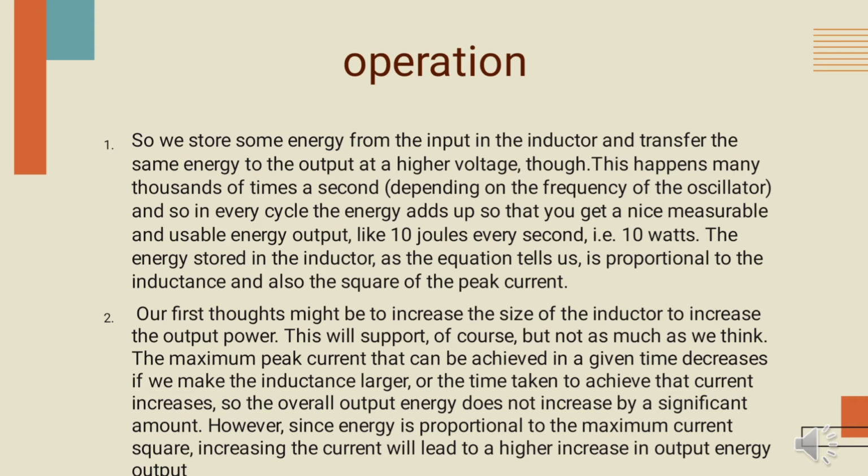The switching MOSFET of the boost converter is always the weak point. And the third one is the inductor. Just any old inductor won't work. The inductor used in a boost converter should be able to withstand high currents and have a highly permeable core, so that the inductance for a given size is high.